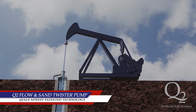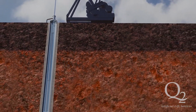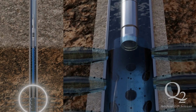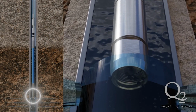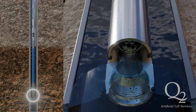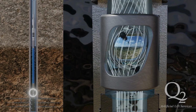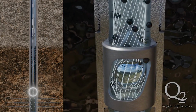This video illustrates Q2's newest technology in our premium sand twister pump design. We utilize two of our patented technologies in this specialty design. As the video illustrates, the flow of the gas and sand goes through the strainer bushing into our patented Q2 Flow one-piece standing cage. The sand-laden fluids are moved through our Q2 Flow one-piece cage around the standing ball at maximum velocity using our tangent flow technology. Sediment is moved into the barrel chamber in a vortex.